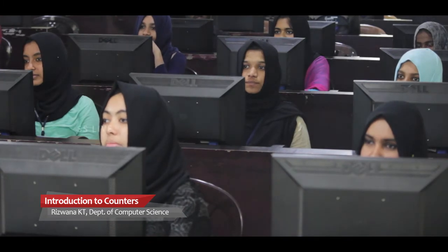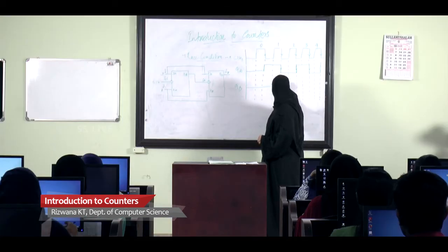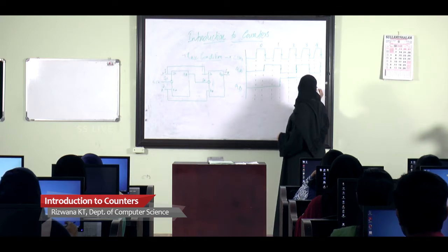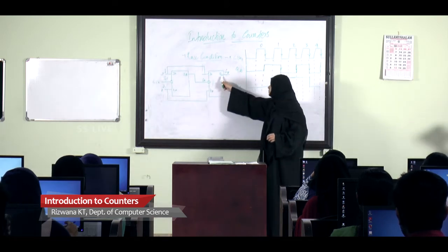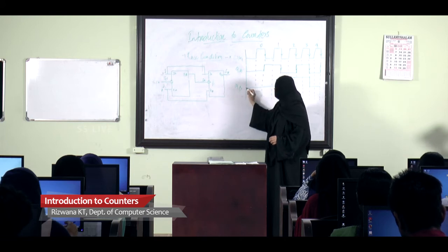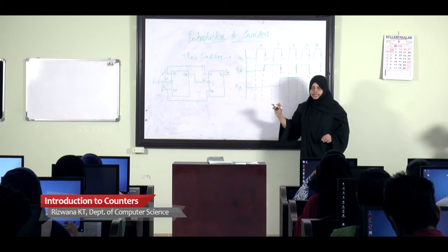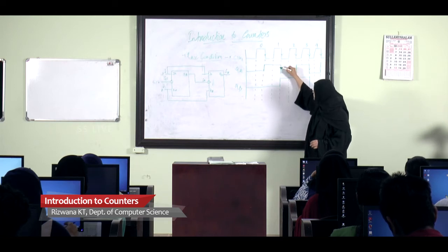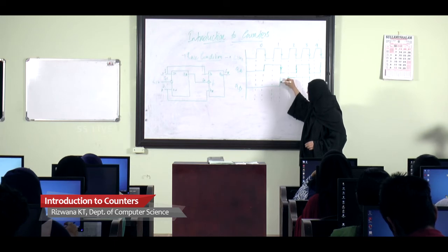See, here it is active low, and QB becomes active in this position. This is how it looks, that is the QB output. This output is available only at this edge trigger, when this clock falls from high to low, at this point QB becomes active.